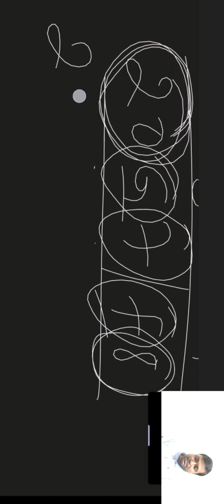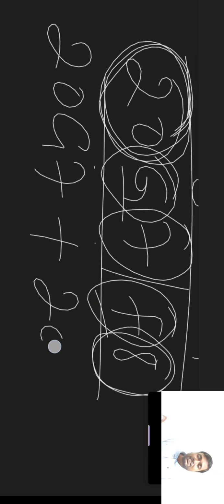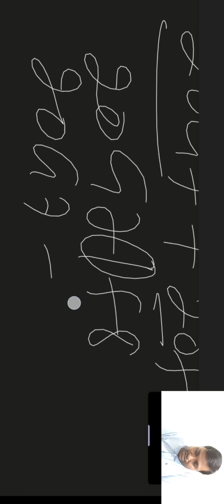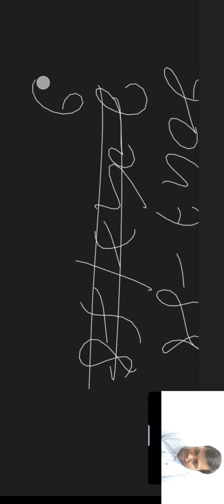What actually it is: a 20G7 hole is assembled with a 20f8 shaft. But we are not writing 20 two times, it will be common. For the same basic size we define the fit. The basic size for hole and shaft has to be the same for the fit. So we are only writing 20G7/f8. In place of slash we can write like this, 20G7-f8, or 20G7/f8, or as we have written already like this, 20G7/f8. So these are the ways we can designate the fit.